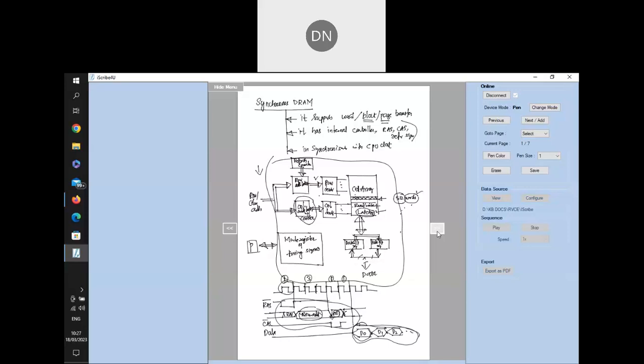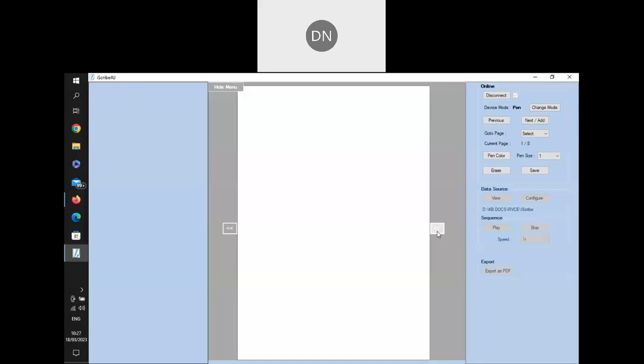So what is the bandwidth, if I ask? The bandwidth will be very high. The more the block size, the higher the bandwidth, because these 6 clock cycles are required only for the first word. So like this, synchronous DRAMs are very popular in the market because they support both word transfer and block data transfer.